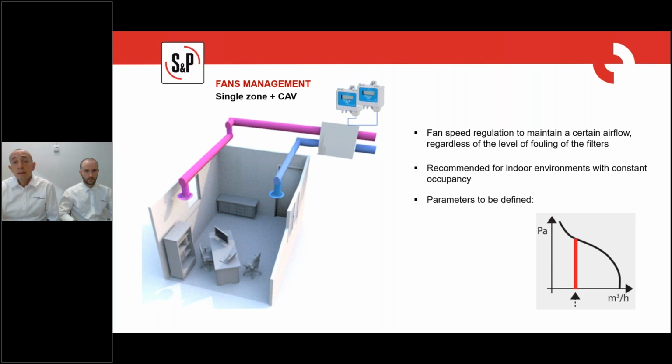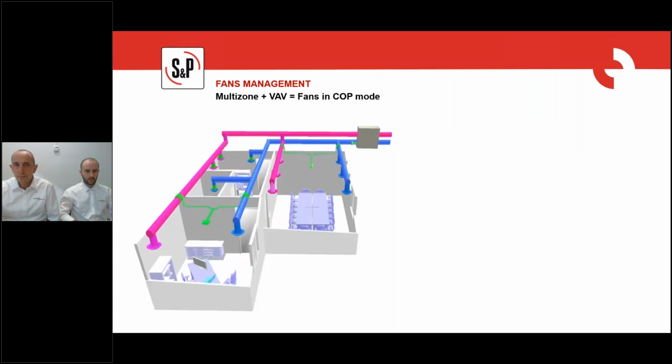Okay. In terms of accessories, in this case, and talking about CAD Compact Advanced, not CAD ProReg, it's different. In CAD Compact Advanced, we have to order two separate pressure transmitters to read the internal airflow, which is passing through both fans. So in all cases, you need to order these two pressure transmitters.